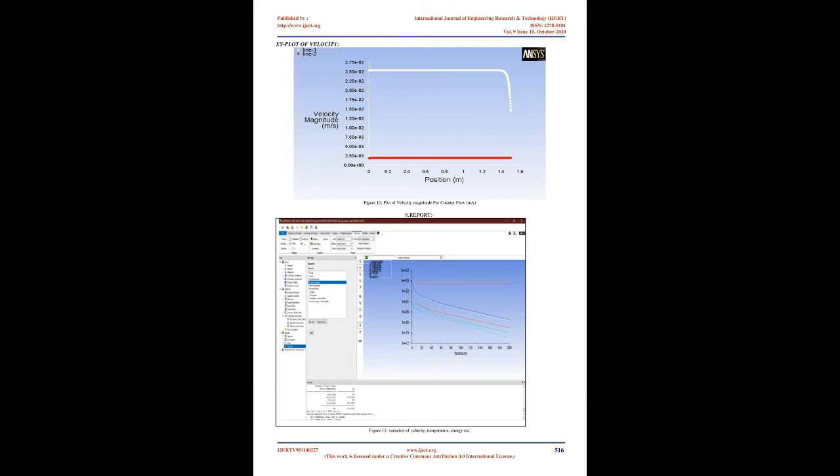The turbulence model wall laws have limitations on the Y-plus values at the wall. For instance, the standard K-epsilon model requires a wall Y-plus value between approximately 30 and 100. For a faster flow near the wall, it must be decreased. Y-plus values for different wall treatments are given in Table 2. The mesh details gave us the following information. Relevance center: fine meshing.